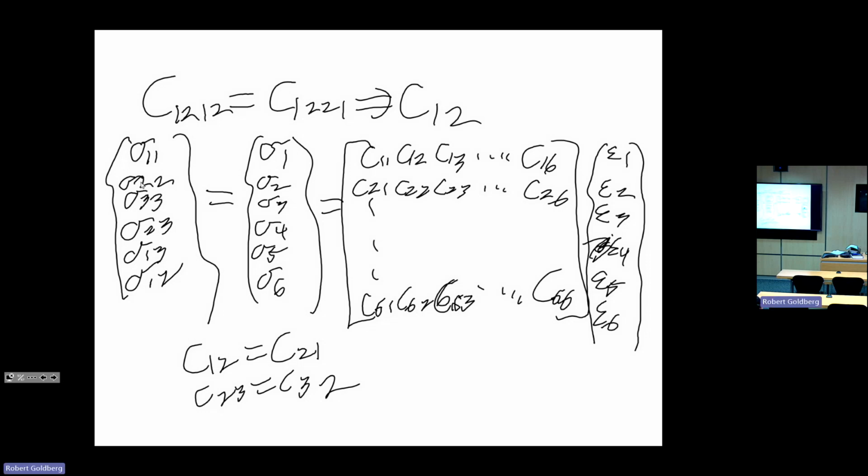And this is all right now the standard tensor definition. Next time, we'll put things in the engineering constants that you're familiar with, like Young's modulus, Poisson's ratio, shear modulus. Then we'll talk about the differences between using engineering shear strains and tensorial shear strains, and what difference it makes in the shear terms in the stiffness matrix. And also, right now, this is a general form. All it is for is linear elastic.